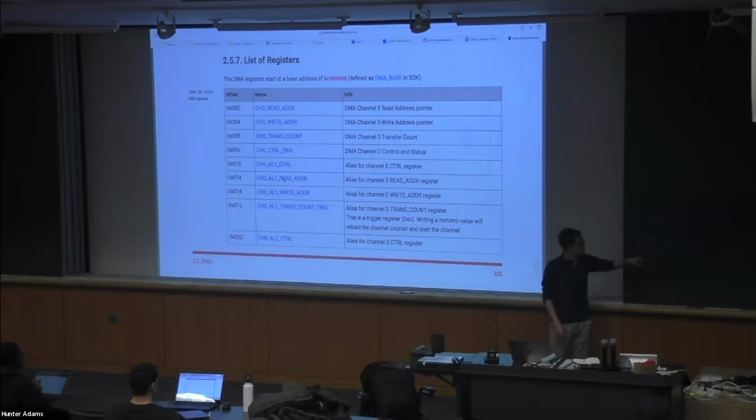When you trigger this DMA channel, either one of these, depending how you have the chains hooked up, the SDK function call that you will call in order to start the DMA channel is non-blocking. You hit that and you carry on. And once you hit that, in the background, totally separate from the CPU, a little thunk will come out of the speaker. Because you want to spend, in this lab, all your CPU time on animation, you want to waste exactly 0 on audio synthesis, we can offload in this lab all of audio synthesis to these DMA channels. So that's why this makes sense in the context of this lab.